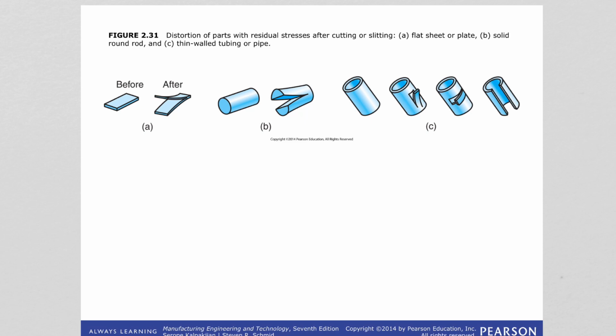Again, a tensile residual stress is very undesirable because, as we talked about, it can lower the fatigue life and fracture resistance of the parts. Because you already have a tensile stress inside the material, and it is going to be difficult for the part to handle external forces, external tensile stresses. Therefore, usually to compensate for that, compressive stresses are introduced to the surface. Usually that is with a technique called shot peening or surface rolling. And we're going to see these.